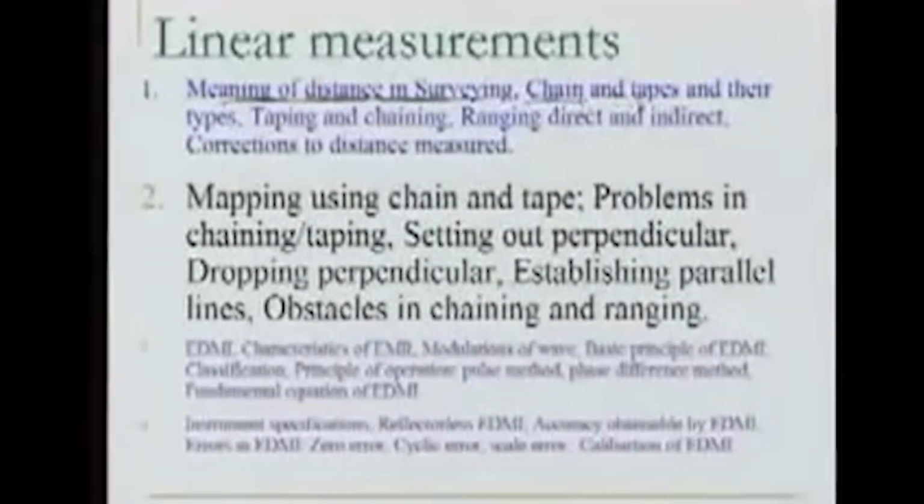Then we saw some instruments. We went to the field also, and we saw some of the instruments. For example, the chain and tape. We saw how the chain was made. It was very flexible, how to fold it, how to unfold it, how to measure the length with the chain. Also we saw various types of the tapes. What are their purpose? Why do we use the tapes?